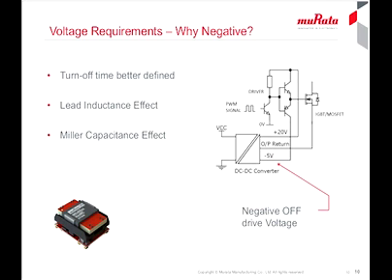We are often asked why the gate drive voltage needs to go negative, because a typical IGBT or MOSFET used in power switching will be off with 0 volts on the gate. There are several reasons, based on the fact that the turn-on threshold can get close to 0 with temperature and time, and it can also change, going lower.